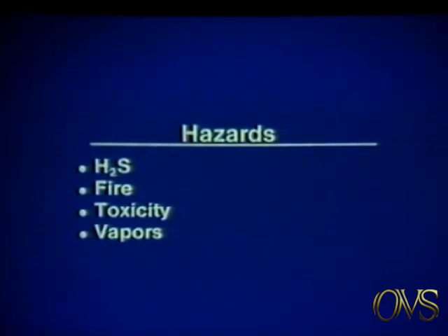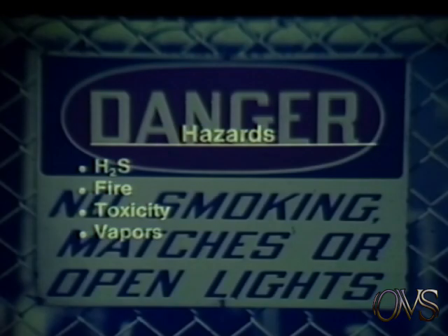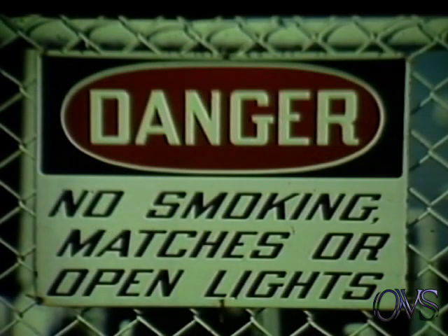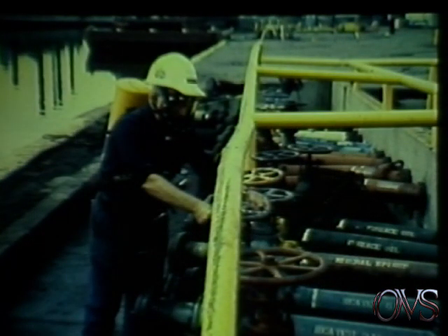Crude oil vapors have also been linked to cancer in laboratory animals. How do you deal with these hazards? First of all, observe no smoking precautions in the area of pumping equipment, manifolds, tankage, and any leak or spill site. Secondly, if you do get crude oil on your skin, immediately wash it off and either dispose of or clean contaminated clothing. Third, seek medical attention if you should, by accident, get crude oil in your eyes or if you swallow it. Finally, make sure that there is adequate ventilation in the vicinity of any crude oil spill, leak, or accumulation within a confined area.